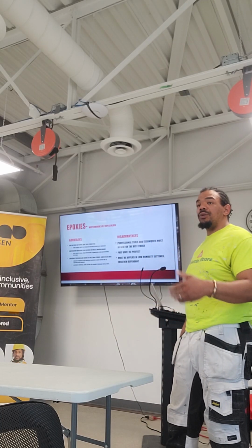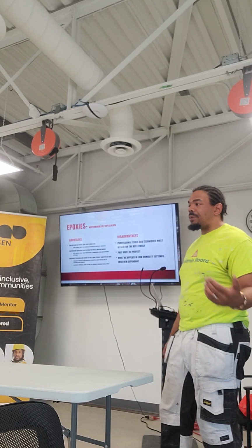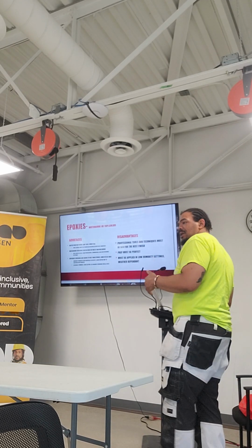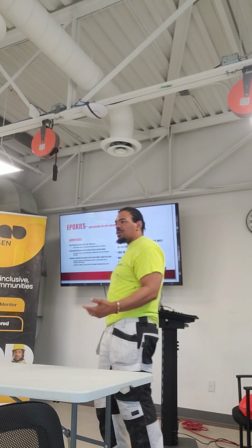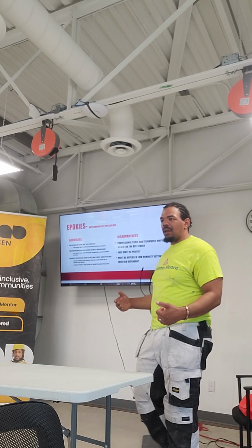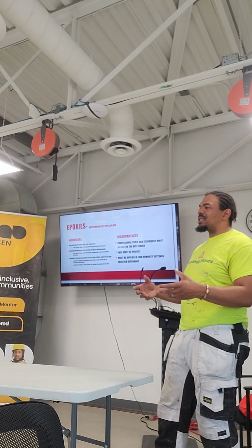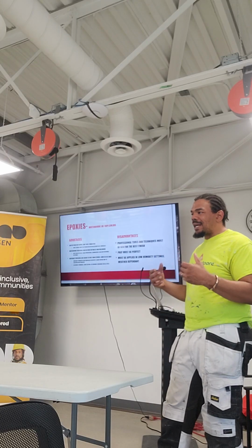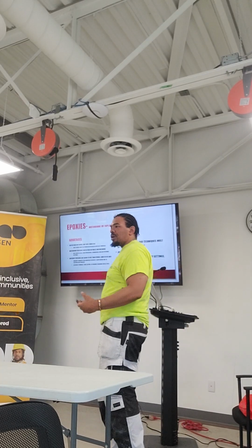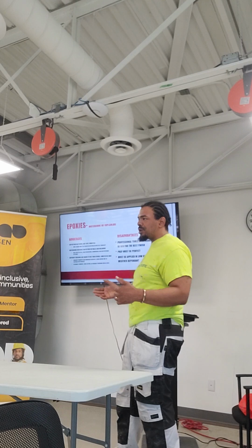That's why they use it so often on floors and gymnasiums, they use it on tabletops, they use it anywhere that you can put an epoxy that would be beneficial. Again, you can use epoxies on walls in the form of waterborne top coats or waterborne paints that can be rolled and brushed. You have amine epoxies that you can mix together, let it induce, and then roll it on the floor. The amine epoxies don't produce as much VOC, so they're not as toxic, but they're still strong and durable, and they last just as long as a 100%. Well, they're not as durable, I won't lie, but they do a great job. They outperform most other coatings.